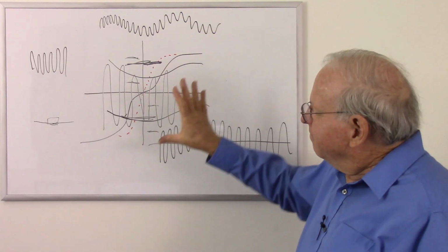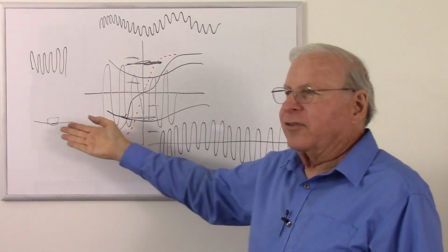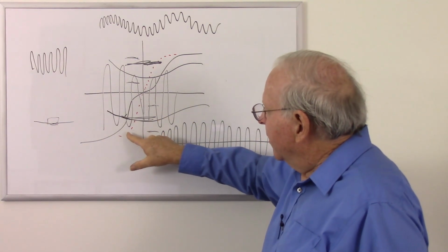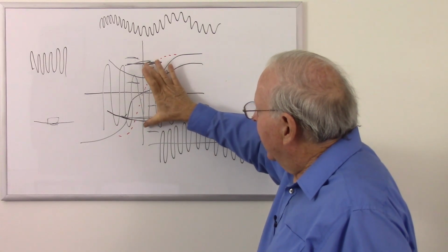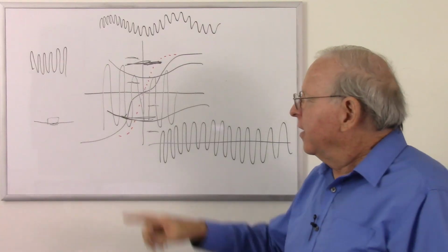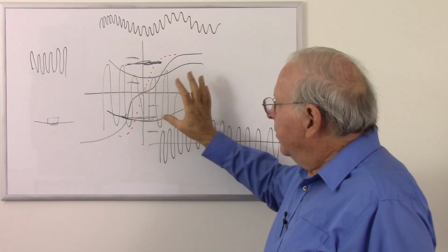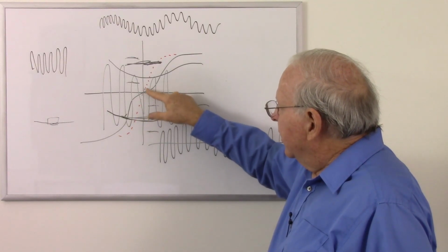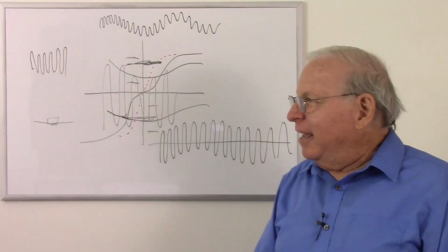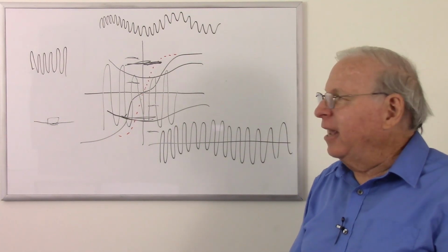It's a little bit hard to follow, but that's the idea of adding the AC to the DC. It erases the tape, but leaves a little residual because of the offset, and so we end up with a nice linear curve as long as we stay below this saturation part of that curve. So this is called the transfer curve, which is what would happen without the AC bias. But with the AC bias, we get this red line that follows a nice linear curve instead of the transfer curve. Hope that makes sense. So now I have explained why we have AC bias on the tape.